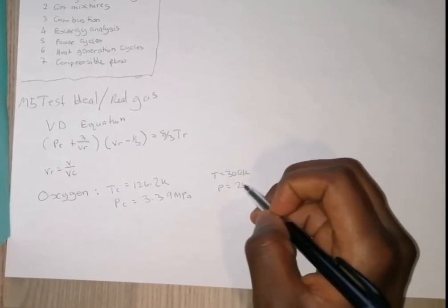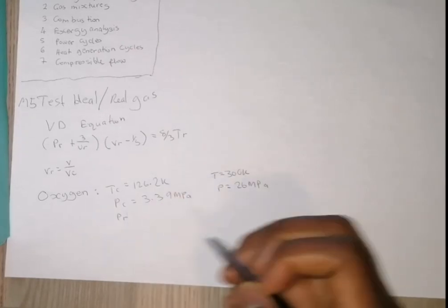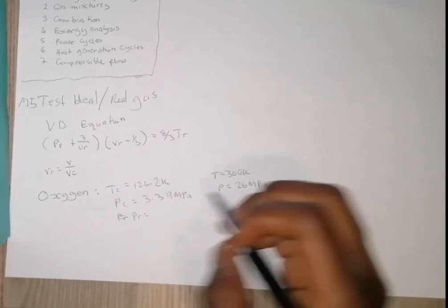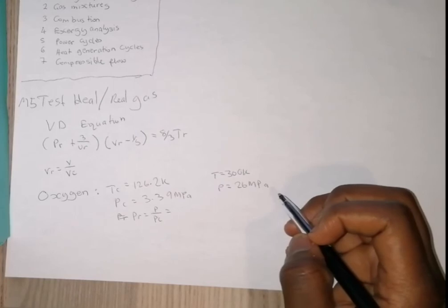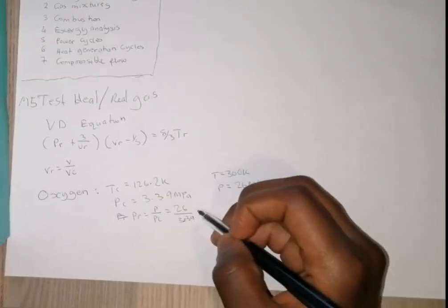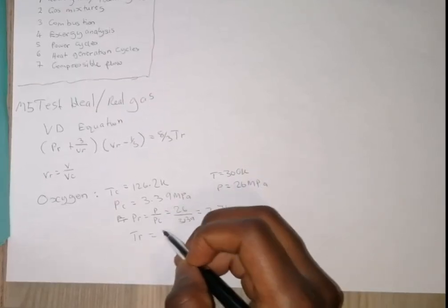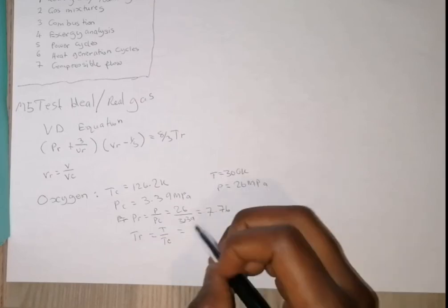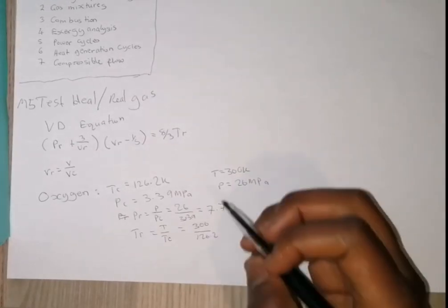and a pressure equal to 26 megapascal. So we'll calculate. To find PR, we're going to have P over PC, which is equal to 26 over 3.39. When we calculate that, it's going to give us 7.76. Then our TR is equal to T over TC. Please look at the units. So it will be 300 over 126.2,